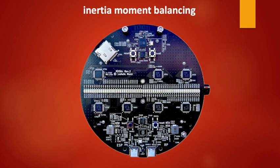The display rotates at a high speed of up to 20 revolutions per second. To avoid vibrations, it is necessary to carefully balance the mass distribution on the display disc. The center of gravity must be exactly in the middle on the axis of rotation. In order to achieve this goal, the components are distributed on the circuit board with a view to symmetry. The components of the microcontroller and the power supply are arranged symmetrically to the vertical axis. Their center of gravity therefore lies on this axis of symmetry.